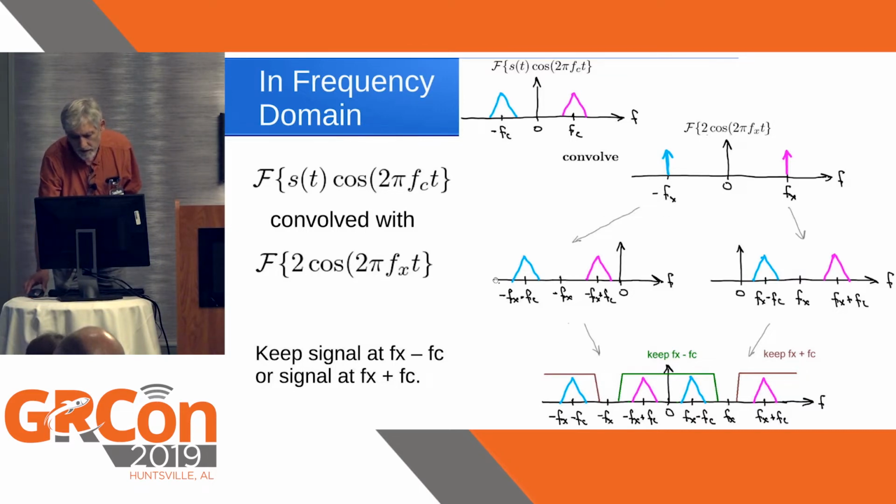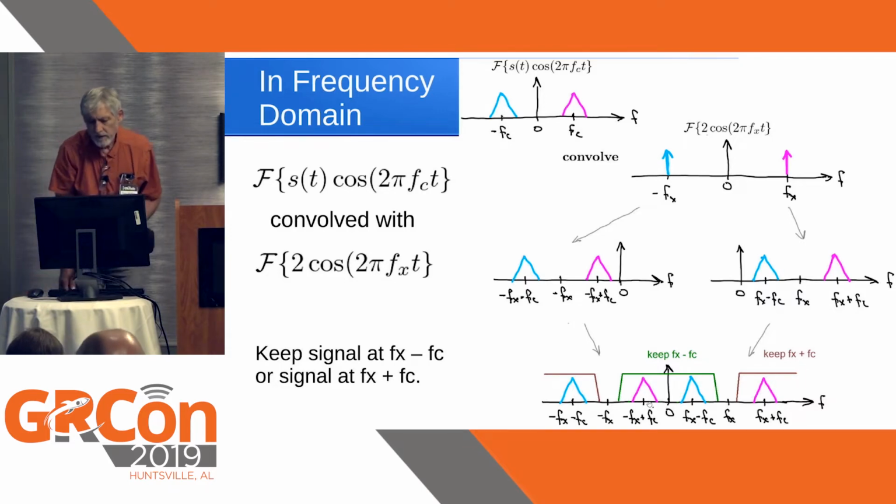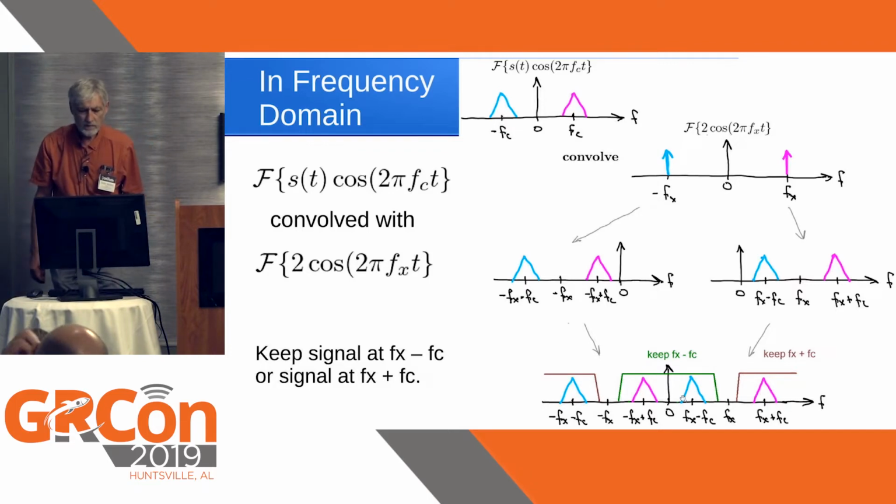And so you're getting this radio signal shifted over to the right here to the positive frequencies. And from this one, you get it shifted over to the left frequencies. And then it gets combined together. Of course, it gets added together. And so you get a new radio signal with actually reversed positive and negative frequencies, but that doesn't matter for a real-valued signal. And you get the other one that's way out here.